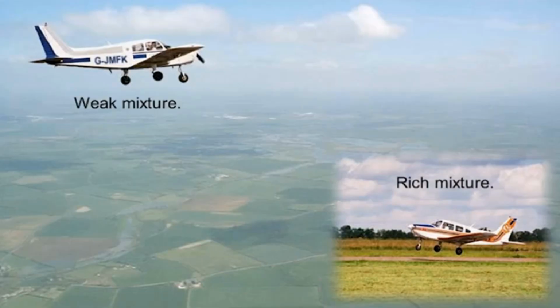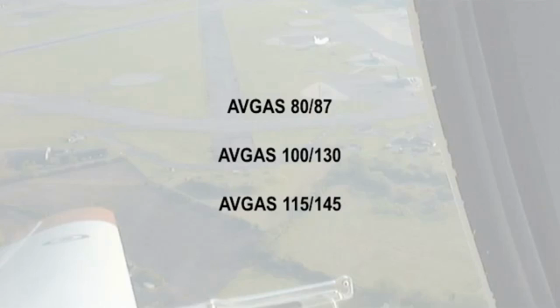Originally, tests were based on an air-fuel ratio which gave maximum detonation, but this condition is not truly representative of the working range of the engine. Maximum detonation occurs with economical mixtures which are normally used for cruising, but for take-off and climbing, rich mixtures are used. It's important to know how the fuel will behave under these varying mixture strengths, and so aviation fuel has two ratings. This is sometimes referred to as the performance number or performance index.